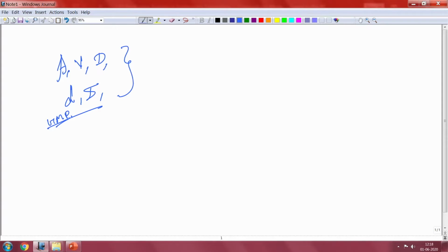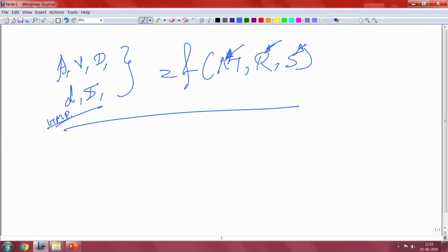In a given region you do not know what magnitude and distance of earthquake is going to come. So, in order to get a wide range of parameters as a function of magnitude and distance, a relation is developed which is a function of M, R and site. M is the magnitude, which represents the source, R is the path, and this is the site. This kind of equation is called a predictive equation, predictive model or predictive relation.